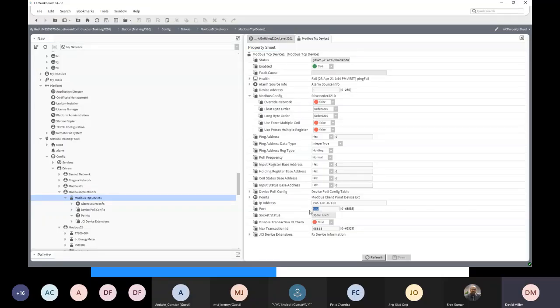In practice you never would, but you could potentially have a super device that does both BACnet and Modbus with the same device, and it could exist on the same IP address, but the Modbus would be communicating on port 502, and the BACnet would be communicating on the BACnet port, the 8084 or whatever it was.